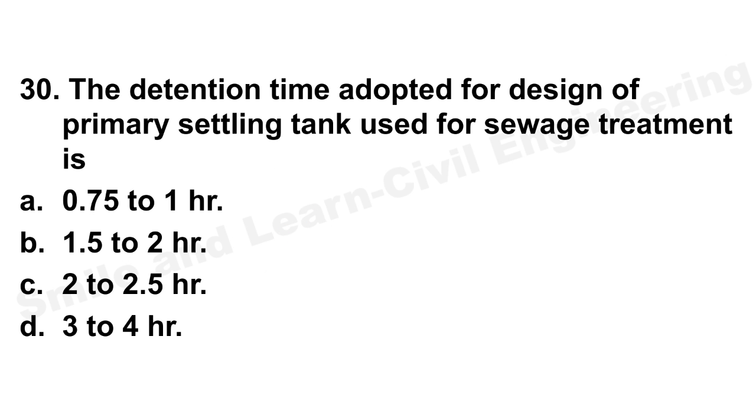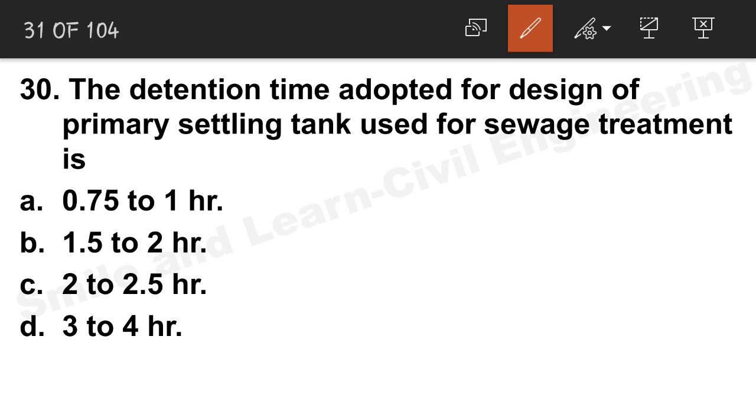Question number 30. Detention time adopted for design of primary settling tank used in sewage treatment. So detention time for primary settling tank, PST, is 1.5 to 2 hours. Option B is the correct answer.